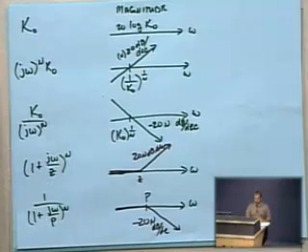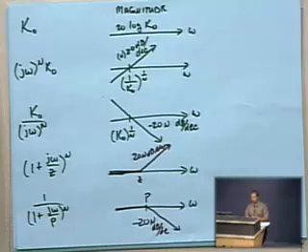And for calculating the initial values, evaluate the transfer function at something close to 0; 0.1 radians per second seems to be pretty reasonable. Evaluate what the magnitude of the function is. Don't forget to find the decibel value by multiplying 20 log base 10 of whatever magnitude you solved for. And then you should have a Bode plot.